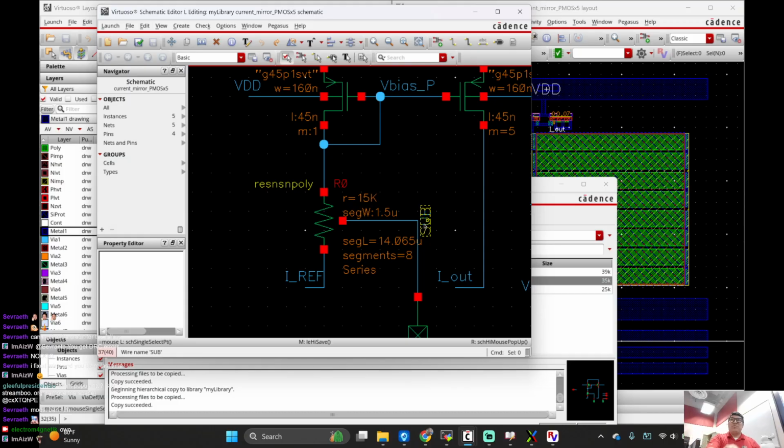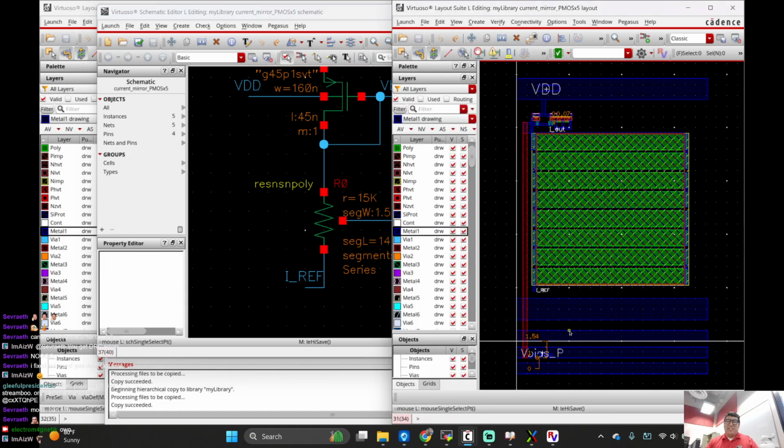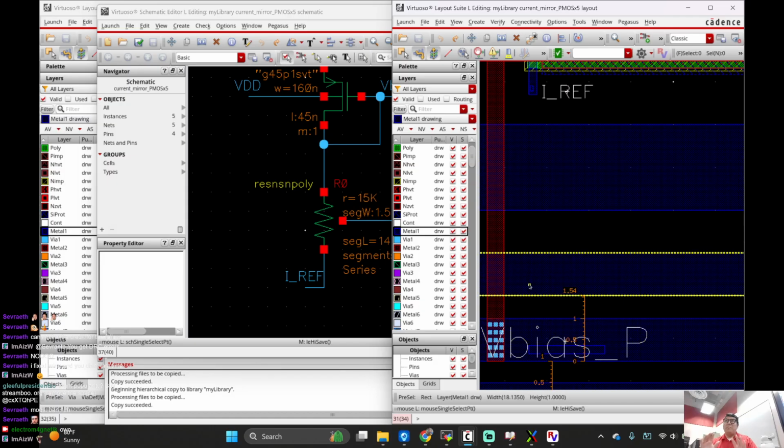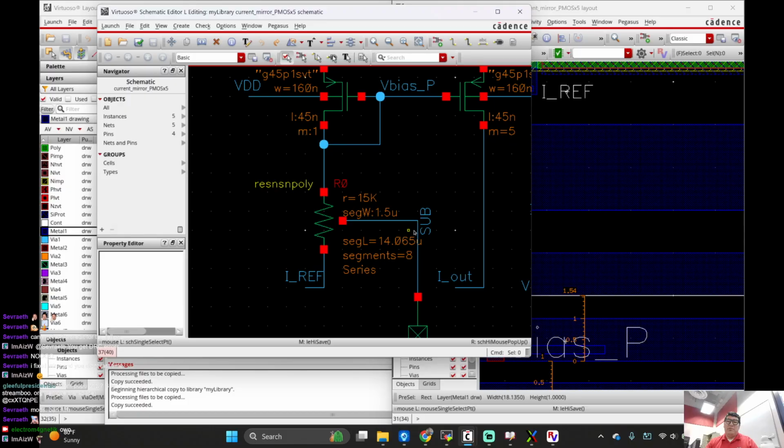But for some reason, for this resistor, even though it doesn't exist, that third terminal, because I declared a pin in the layout, it said it does exist in the layout. It doesn't exist in the schematic. It's telling me in the schematic it doesn't exist. But I have to feed it this. So how do I fix that? Just make it not exist here. So there's no sub pin, even though there's a sub label here. Or better yet, if I just delete that, I think it should fix some other problems. All right? Any questions?